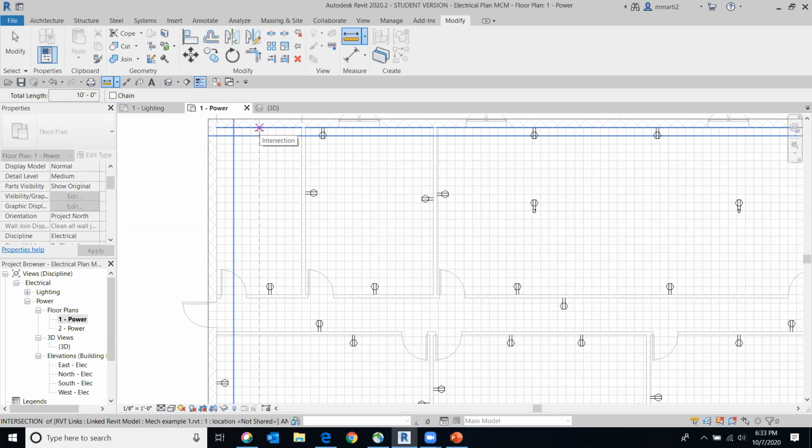I'm not actually going to need it in the hall, in the stairwell, but I'm just showing you where it would be. Technically, there would be a landing right here, and we would put one here. Since I know this is a 10 foot space, I can just put one outlet in that spot right there. And usually I would put that at the midpoint of that wall.